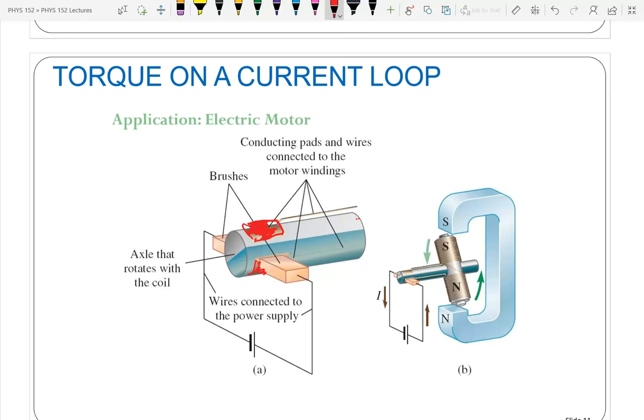And so you have power coming from your battery that makes this side always positive, this side always negative. And when the brush is touching this, then the blue side is going to be the positive side, and the gray side will be the negative side. Does a half rotation, and the brush is going to switch from one connector to the other one because the connectors are rotating with that axle. And so what that's going to do is switch the direction of the current every 1/2 cycle.